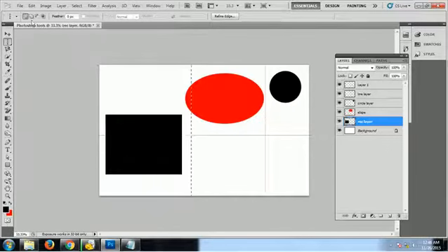For this we have four options here. Just selecting this one, it's for adding to the selection. If I take another tool and click, it will increase the selection this way. The previous one is this, and I am just adding this selection, so now it becomes this much selection. Okay, but we need to cut this out of the area. And this is another option, subtraction.